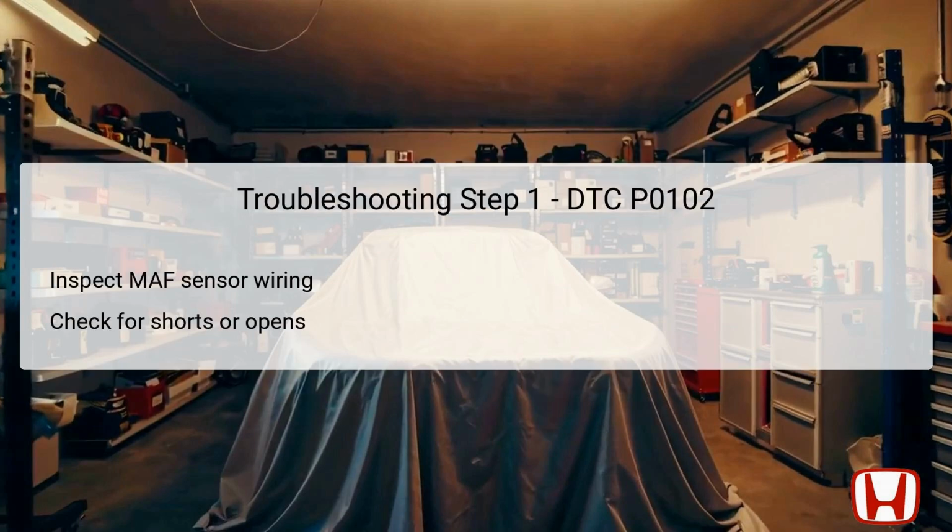The first step in troubleshooting DTC P0102 involves a visual inspection of the MAF sensor wiring. It's essential to check the wiring for any visible signs of wear, fraying, or damage. Look closely to determine if the MAF sensor VGP line has any shorts to ground or if there are any breaks in the circuit. Ensure that all connectors are securely fastened and look for any corrosion that might affect conductivity. If any wiring issues are detected, repairs should be made before proceeding with further diagnosis.